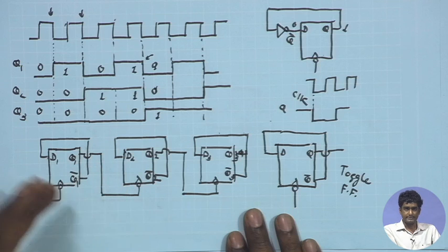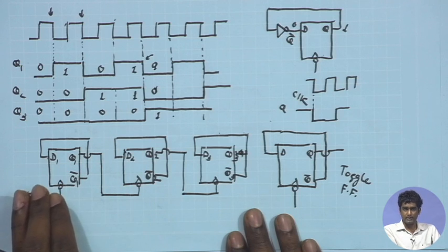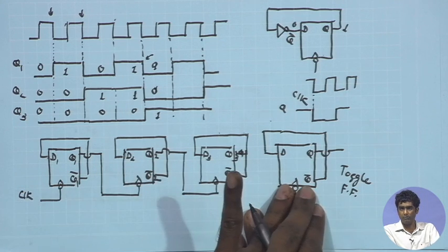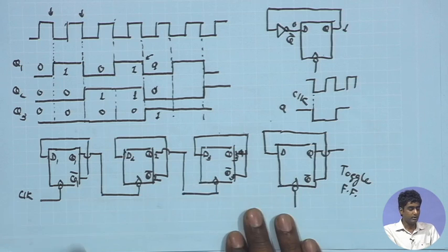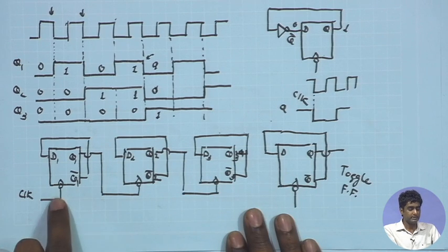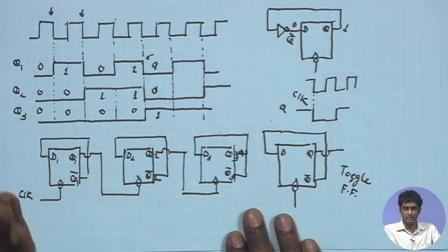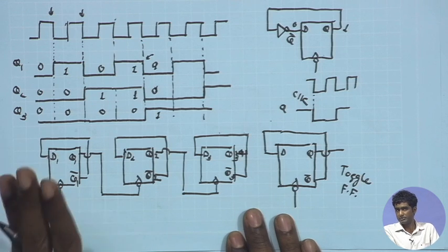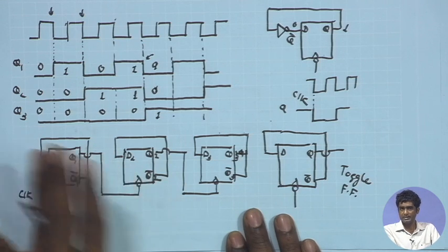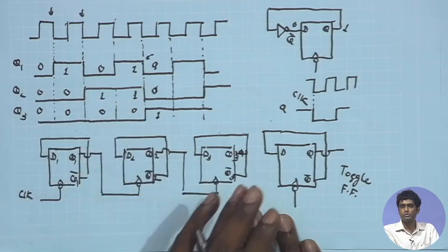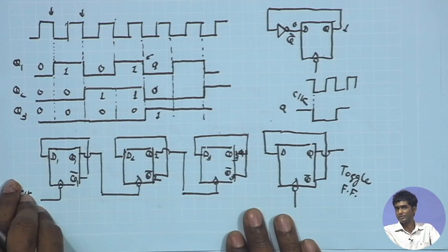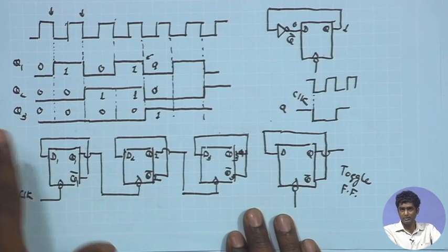So, a synchronous circuit is one in which a single clock governs the transition for all flip flops. So, here the main clock is governing the transition of only the first flip flop, the other flip flops are not strictly changing their state exactly at the negative transition of the main clock, they are changing their state at the transition of the respective inputs. So, with respect to the main clock, they are asynchronous, they are changing asynchronously. So, this is an asynchronous counter or a ripple counter.